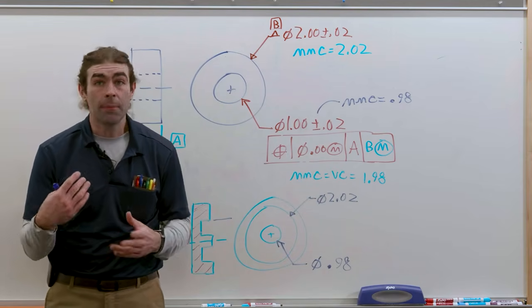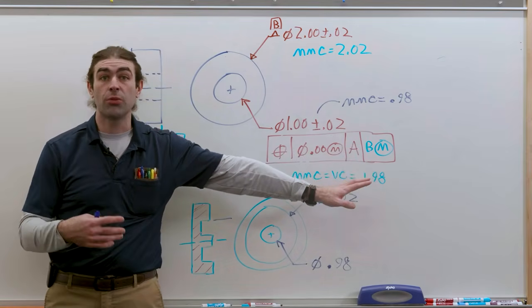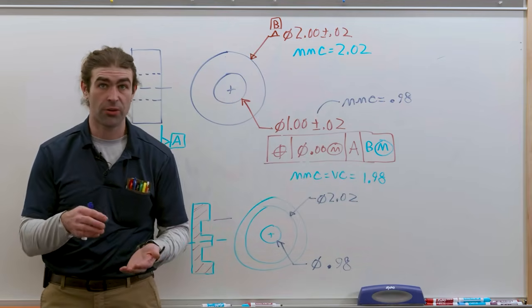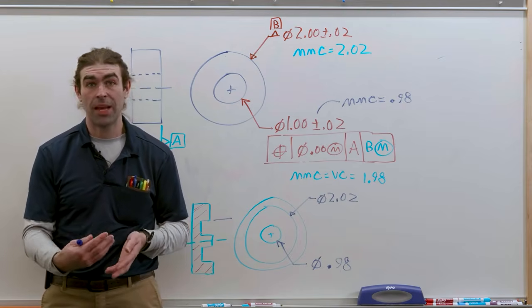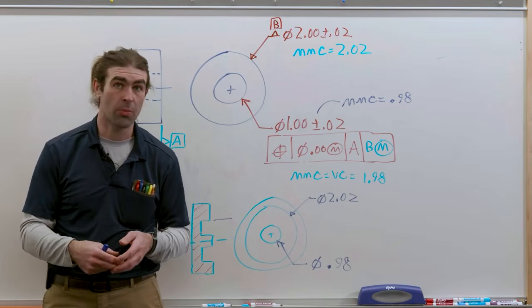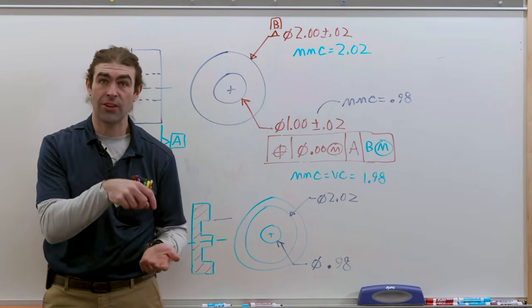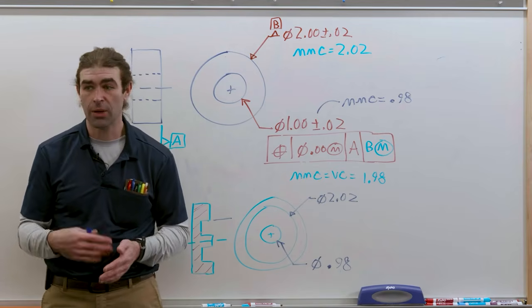Okay? So these aren't always used, but they are a technique to save money at inspection. If you can set your tolerances like this, you can automate inspection to a pretty serious degree, right? You could have a robot drop this washer, this donut, into a gauge, and if it fits, it's good. If it doesn't fit, it's bad. It goes in a different bucket, okay?